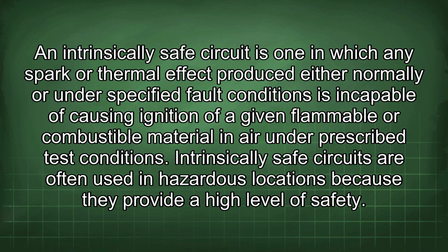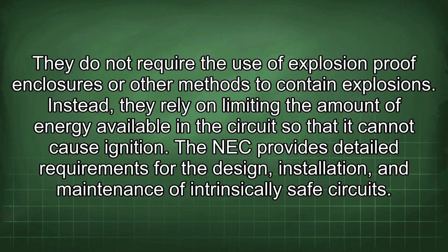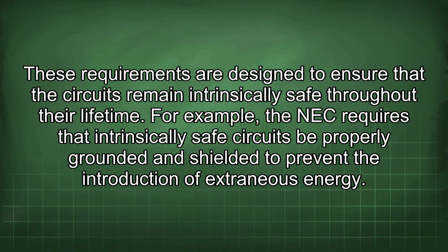Intrinsically safe circuits are often used in hazardous locations because they provide a high level of safety. They do not require the use of explosion-proof enclosures or other methods to contain explosions. Instead, they rely on limiting the amount of energy available in the circuit so that it cannot cause ignition. The NEC provides detailed requirements for the design, installation, and maintenance of intrinsically safe circuits. These requirements are designed to ensure that the circuits remain intrinsically safe throughout their lifetime.